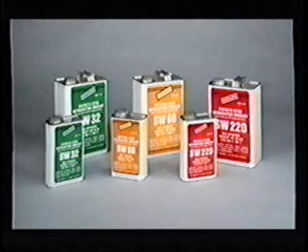You must be careful when purchasing replacement oil. Of the 3 R134A oils shown here, only the oil in the center is for OEM semi-hermetic compressors. The oil on the right is for 104 mm screw compressors, and the oil on the left is for R12 retrofits. When additional oil or a complete oil charge is required, use only the Carlyle approved oils.